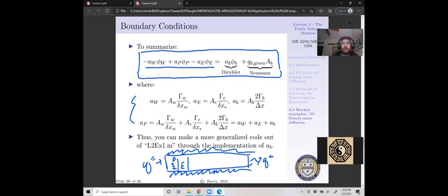they exist. So in our lab, we do waste heat recovery of exhaust gases. So you're actually providing a flux to the hot side of a heat exchange system with thermoelectric generators. And on the cold side, you basically have a convective boundary condition. We're also specifying a flux. So your top side's really defined by h and a free stream, and your cold side is defined by h and a free stream. And these two temperatures at the bounds of the system and all temperatures throughout evolve as a function of those supplied fluxes.